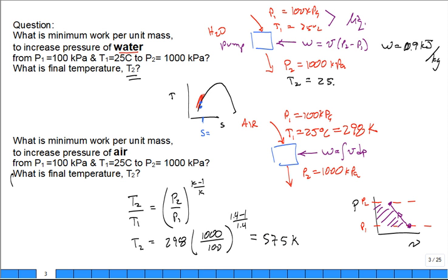If I want to calculate this work, this way is conceptual. I have an illustration, but I can just do an energy balance, and I know that the specific work is equal to h out minus h in. True or false? Add constant specific heats, cP times (T2 minus T1). True? Constant specific heat value from memory for air, cold.